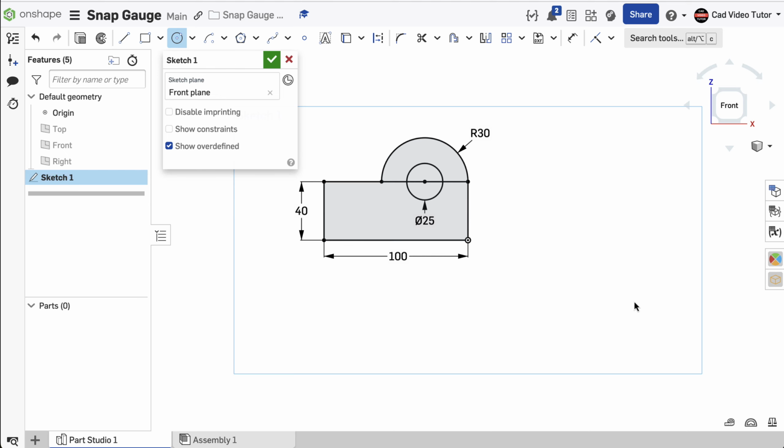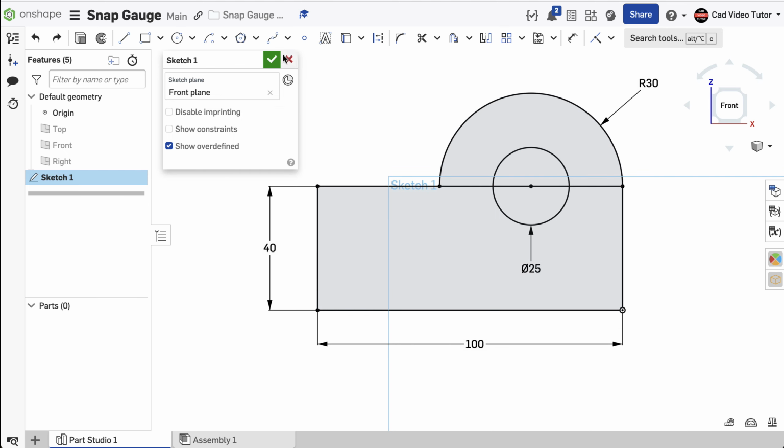From the toolbar, choose Corner Rectangle. Click in the middle of the existing rectangle and create the new small rectangle without touching any other lines. Enter 35 for the length and 15 for the height. Next, we need to align the center of the slot with the center of the nose.